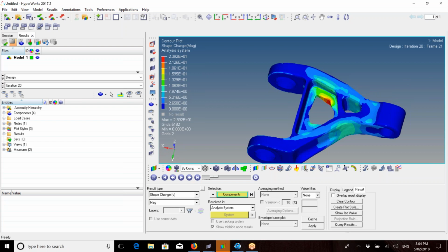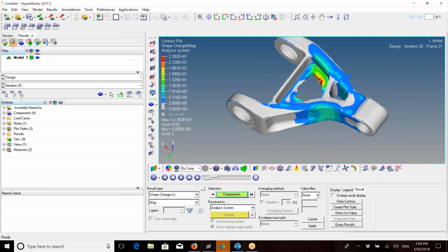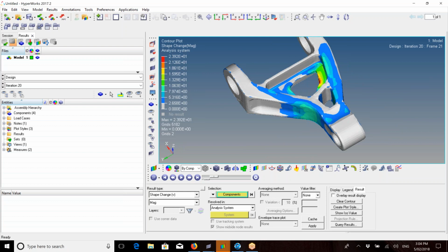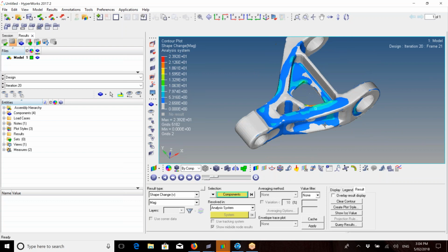And also with the legend here, one good way is you can change the colors of that simply just by clicking on the section you want to change. So I'm going to change the bottom bit, just turn it to a gray. And that helps you see where the material has been added by cutting out the medium blue to a dark blue. Now just put it to the lowest case gray, and we can get a better look now of how this is actually being created.